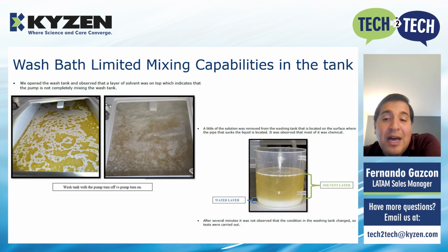This was making an effect in the concentration percentage readings, which caused them to be lower than expected. This was being experienced by the customer also with the competitor cleaning agent, and they were constantly adding extra chemical, looking to maintain the desired concentration. All this behavior was provoking a higher consumption than usual in the process.